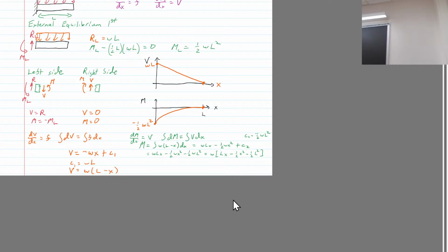Well, that's not true, because the tau's not just M, it's more than that. But for this, we're talking about the bending stress, so it's sigma actually. There's also tau because of V. So PZ is the shear force. But then there's no transverse shear stress because it's at the top of that cross section.